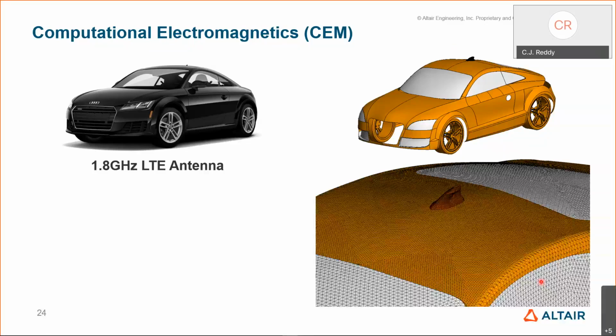In CEM terminology, these triangles are called subdomains. In these subdomains, we solve Maxwell's equations because now we know the shape and we know how to solve it for that particular shape and how to apply the boundary conditions there. Once you solve it, you can combine all those solutions together to create your currents.